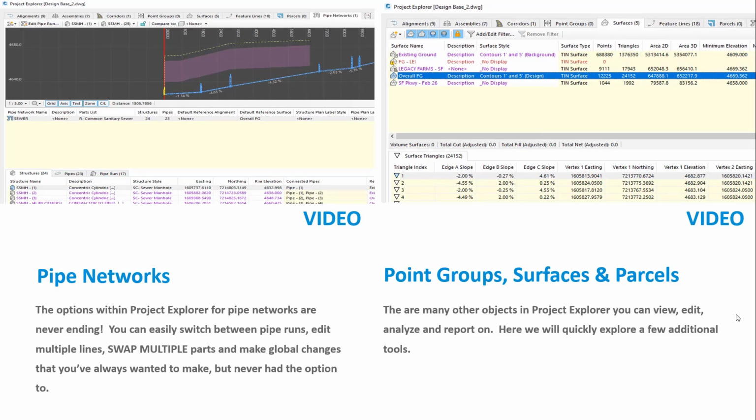So for this next portion of the demo, we're going to look at pipe networks. There's some great tools in here, tools I wish Civil 3D has had for a long time. Stuff as simply as grabbing one manhole and grabbing 10 manholes down the line and saying, grade this at 1%, grade this at 0.5%. Couldn't do that before. Gravity pipe, swapping multiple parts at one time and making those global changes that you've always wanted to, but never had the option of doing that. So let's jump into pipe networks and see some of the exciting tools in Project Explorer.